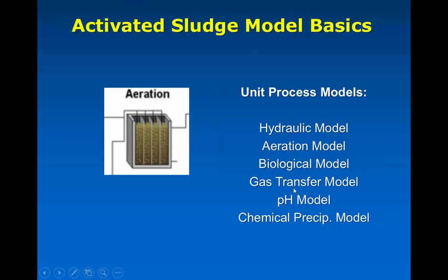We have a pH model in our Mantis 2 model where we now have to keep track of, in addition to everything I've already said, on top of that, we're now keeping track of things like calcium and magnesium and potassium and all the other ions, cations and anions that are there that become part of the electroneutrality balance. And so, they're sort of building upon levels of complexity here.